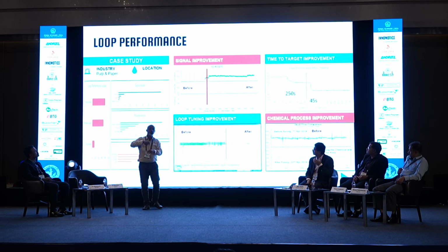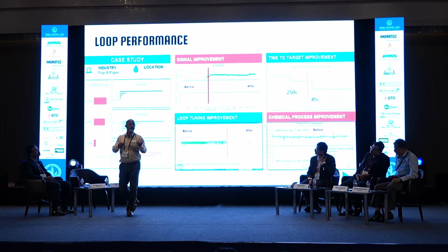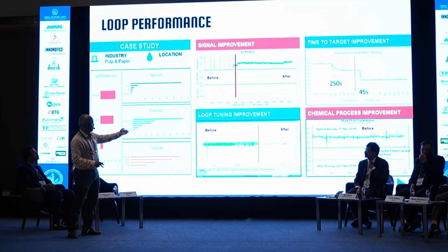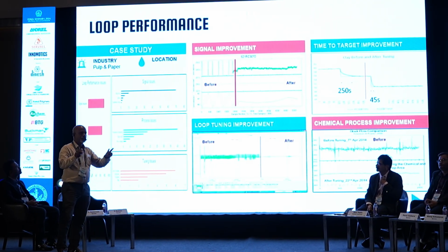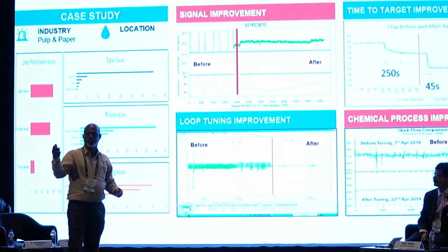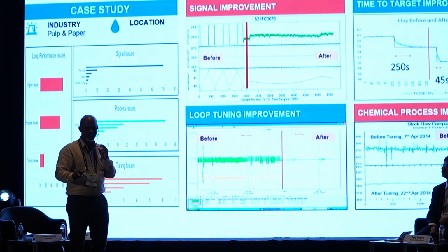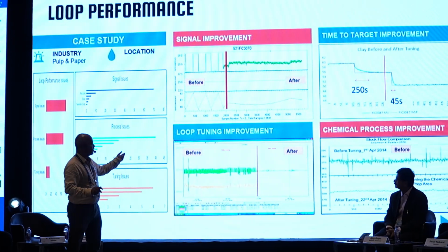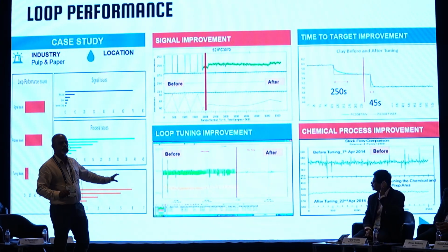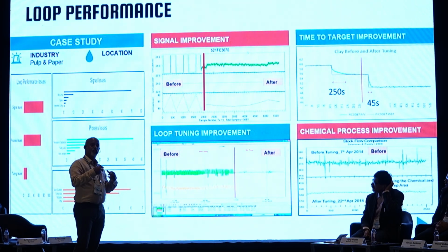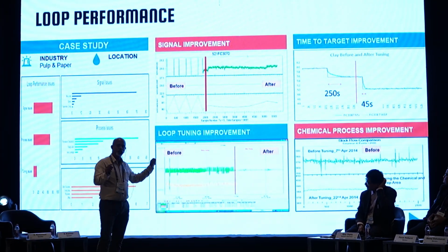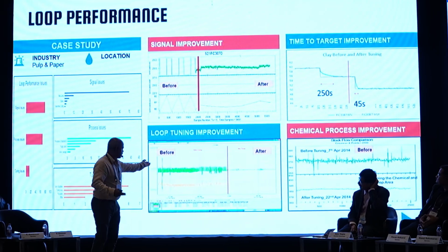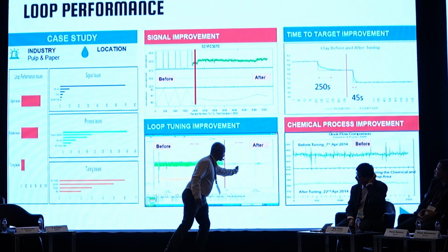When there is valve variation, you are inducing energy or variation into the machine, which will definitely cause problems. Same way, for example, this loop tuning. This is very small, 2% level variation. This is very big, not small. 2% is very big. That gives you a lot of issues, right? When we do the right tuning numbers, if you understand the process, then adjusting the tuning numbers is very small, very simple. There are only 2 numbers. When you do, you can see the improvement in a straight line, right?